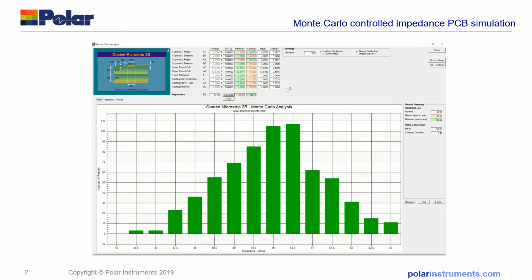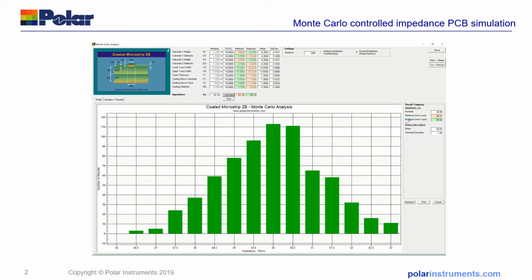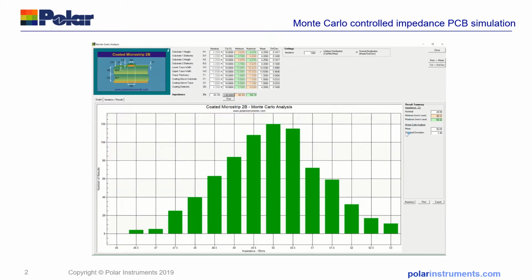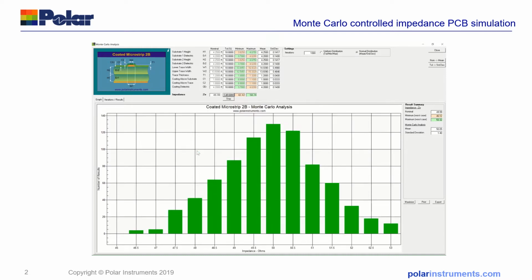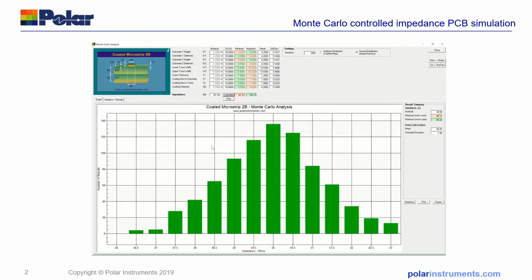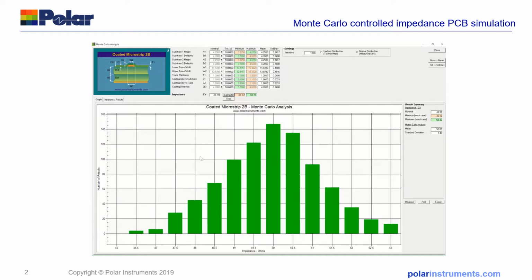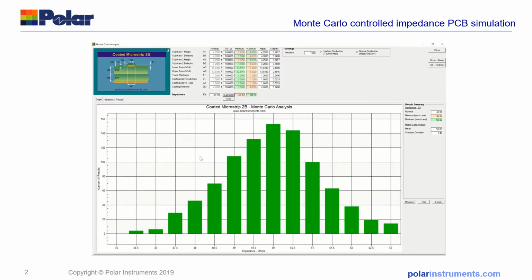When the analysis is complete, then you'll see the summary of the nominal, minimum worst case, maximum worst case, and the Monte Carlo analysis showing you the mean and the standard deviation for the whole of the production run. Here you can see in the background the waveforms are building up very nicely into what you would expect is a normal distribution, as each parameter is swung at random through a normal distribution.